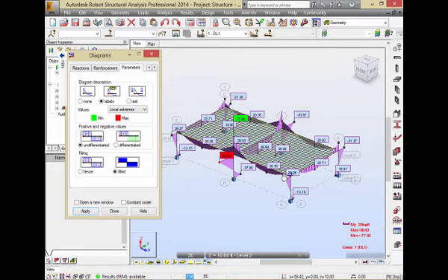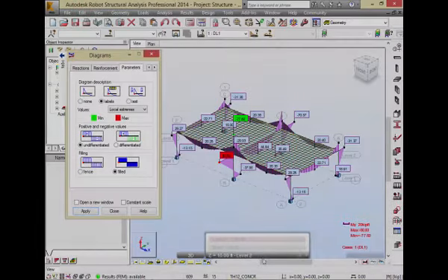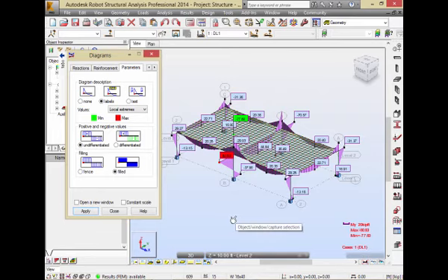These are the bending moments on each of the different members, on the columns, as well as on all the different individual members. I can see it's minus 22, it's minus 20.35, and what is that at the top there? The extreme there is minus 77. That's the worst. The worst case right now seems to be the middle beam, where it has things joining from the two sides. It's got a lot of load coming from two sides, so that seems to be the most heavily loaded beam right now. That's the center beam coming through.